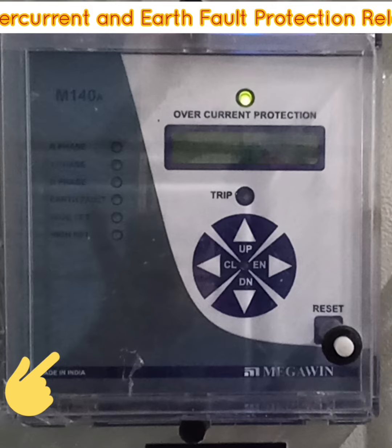An electrical overcurrent relay is a protective relay that is designed to detect overcurrents in an electrical system and provide protection against short circuits and overloads. Overcurrents can occur due to various reasons, such as equipment failure, external faults, or incorrect system operation. The electrical overcurrent relay monitors the current flowing through the system and operates when the current exceeds a preset level, indicating an abnormal condition.